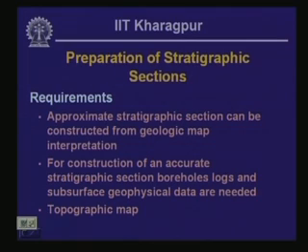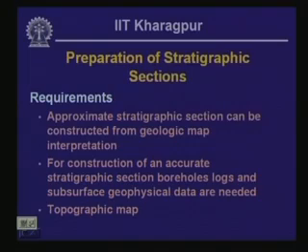If you need to construct an accurate stratigraphic section, then boreholes need to be drilled and accurate logs identifying different stratigraphic units within the borehole will have to be prepared. And also in this context one might use subsurface geophysical data in which one can see different stiffness properties, stiffness contrast of different stratigraphic units underground.